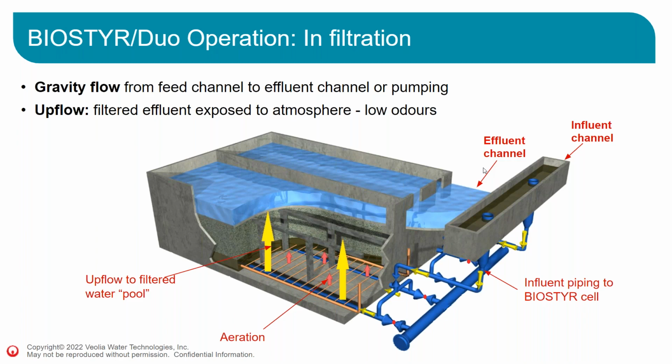The main advantages of this flow are that the filtered water is exposed to the atmosphere, so there's no odor related to the water treatment because you are in contact with clean water instead of the raw water. And there's little pumping required, since the only pumping required is to get the flow down the cell. Once the water is down, it's all gravity flow.